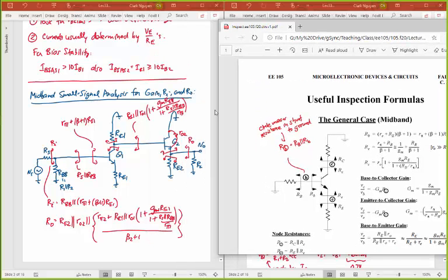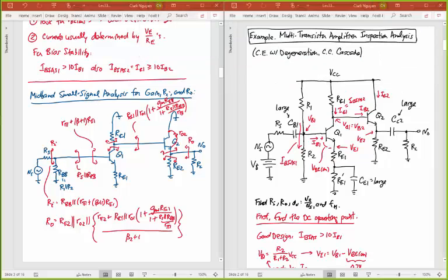And so if I go back to the circuit here, all of this resistance looking out of the base is all of this stuff, which I copied right there. And then all of that stuff is divided by beta plus 1. Okay, and that would be the beta of transistor 2. Now in this problem, I'm assuming both transistors have the same beta, but that's where all of that comes from. So hopefully that's clear. I'm just going straight off of those inspection analysis equations there. Okay? Okay, good.